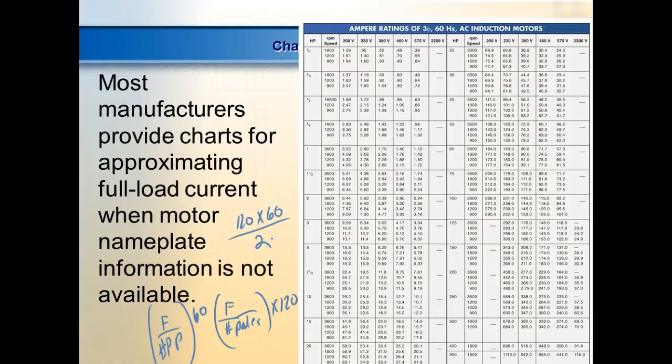So y'all understand where the 120 came from? What we're doing is going from cycles per second to revolutions per minute. And this is not the speed of the motor, this is the speed of the field. I did the 120 times 60 divided by 2. You got 7,200 before you divide. I got 7,200 divided by 2. Sounds like you're dividing by 4, so you're doing something there.